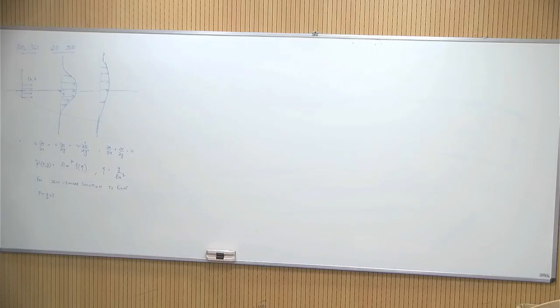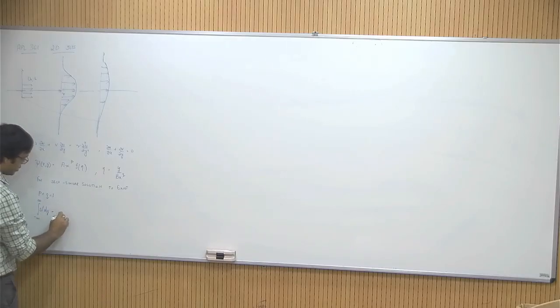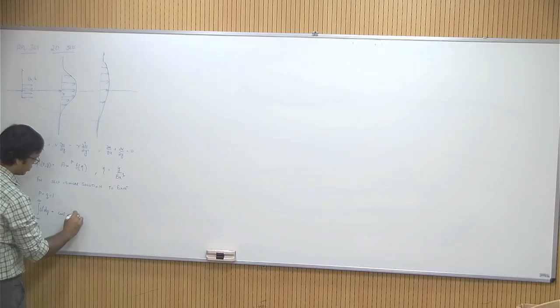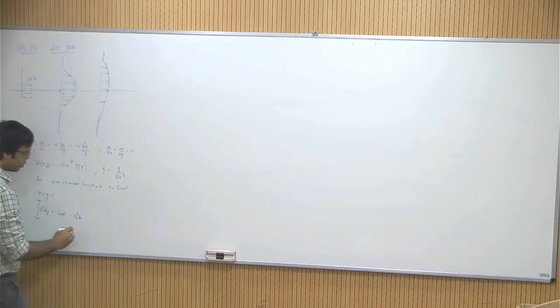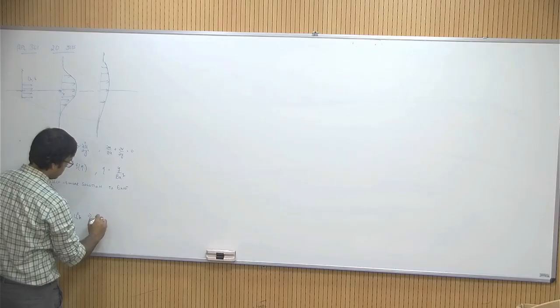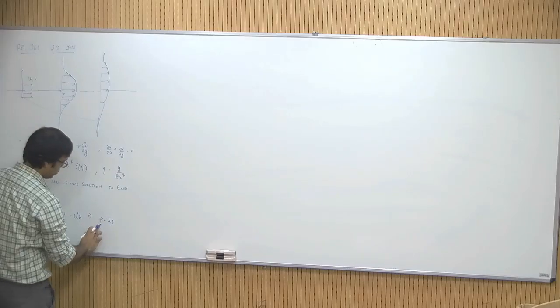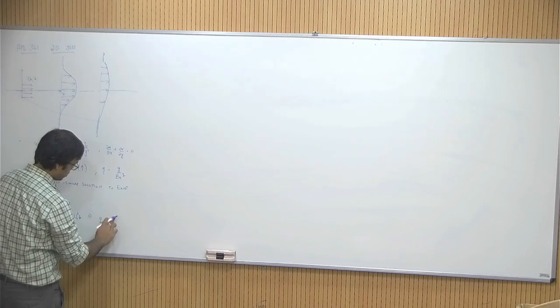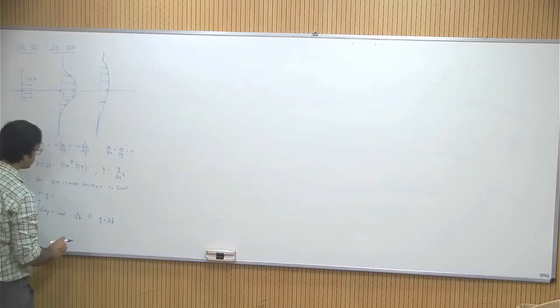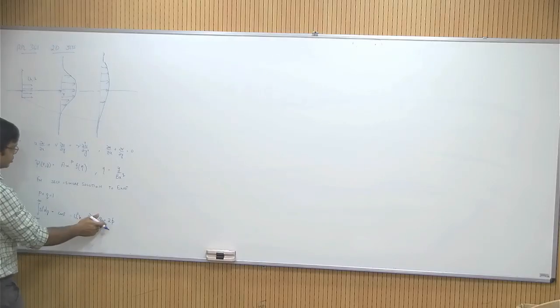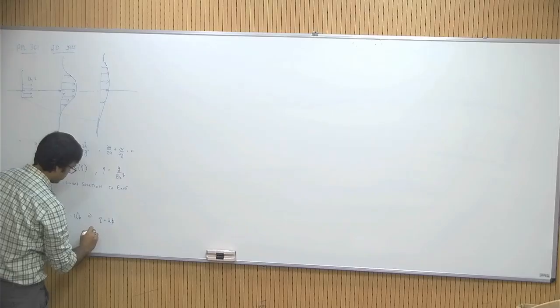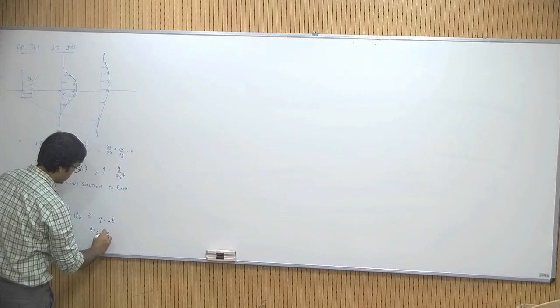Okay, and then we had shown that for a jet you have the momentum flux as constant. Basically this is equal to u naught square times h. So from here we had derived that, what did we derive? q equals 2p, something like this. Okay, and so by combining these we saw that q is 2 by 3 and p is 1 by 3.